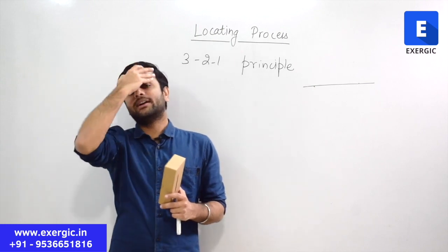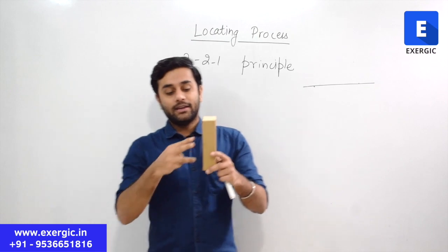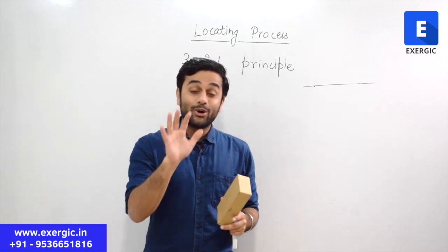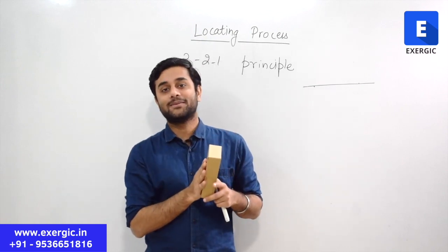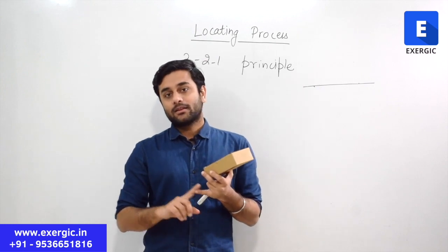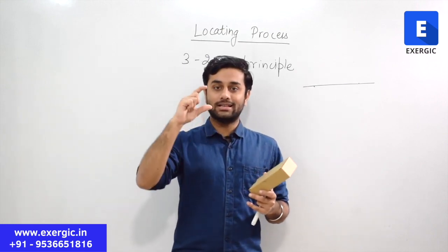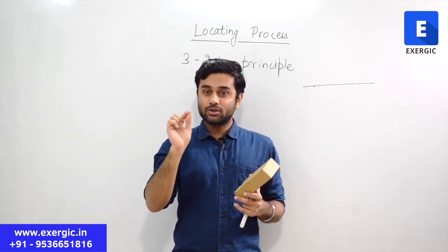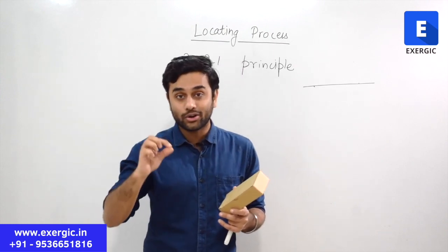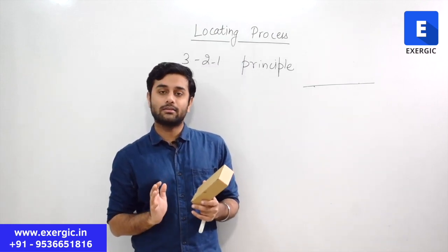But conceptually, it is very interesting. If you try to add the 4th point or the 4th pin, you may not be able to define the plane. Let me tell you how. Firstly, recall the concept of metrology. Every pin that is made is not accurately made. There are tolerances given. All the pins are not of the same desired dimension.